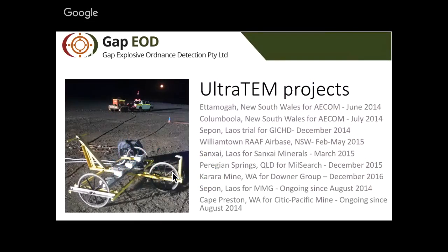So this is, instead of using magnetometers now, we're starting to use EM systems. So we've built our own 3-component cubes. These cubes here are actual coils. They're 3-component coils. And we use those in an array, as you can see there, similar kind of line spacing and sampling to what you'd be using for the magnetometers. You're looking for the same targets, very small targets, reasonably shallow depth.